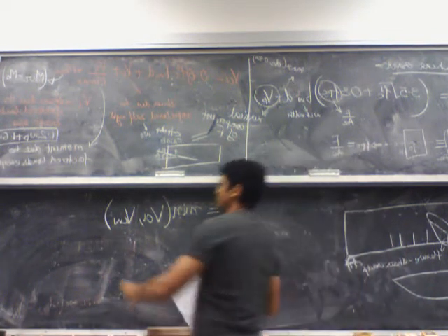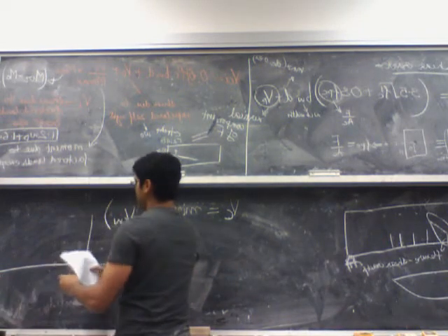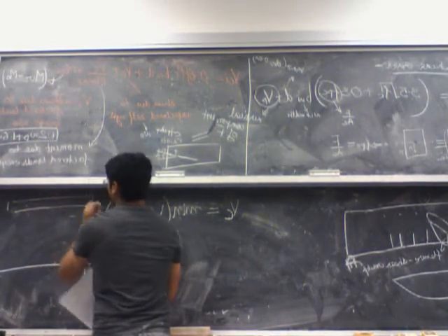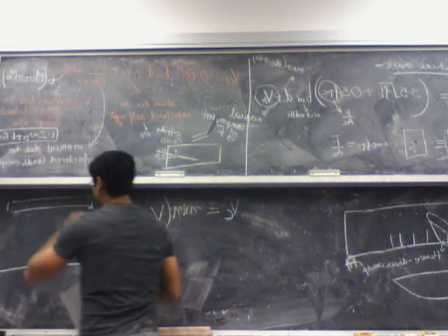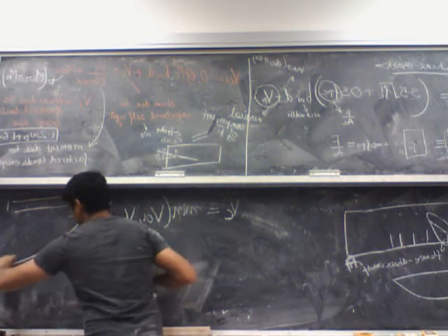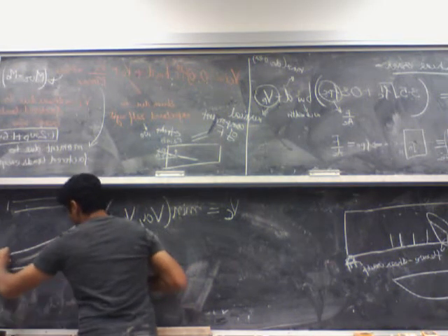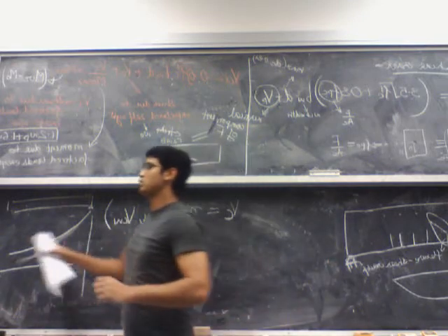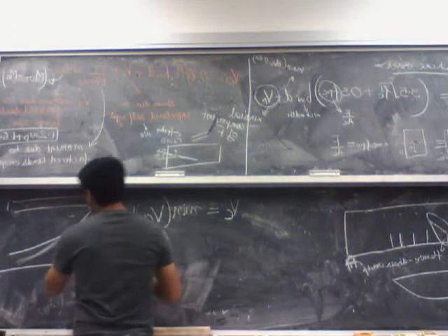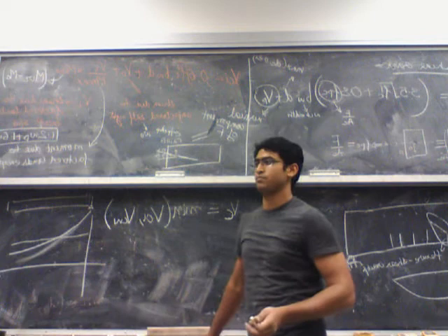And what actually happens is if you draw both of them, so this is, let's say, distance x. At x equal to 0 is your first support, and x equal to L is the second support. What you'll see is VCI will decrease as you go away from the support, and VCW remains more or less constant. It's not exactly constant, but it remains more or less constant.